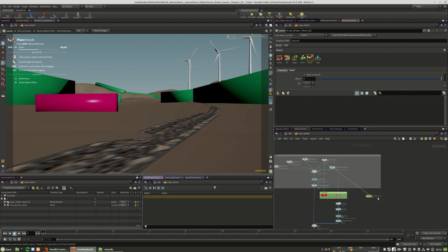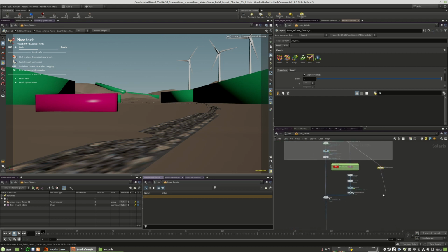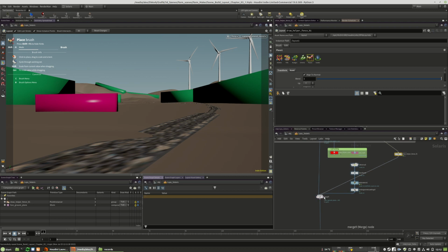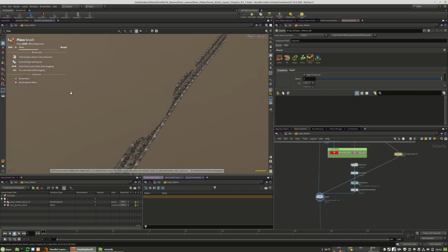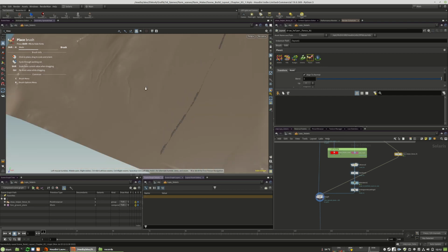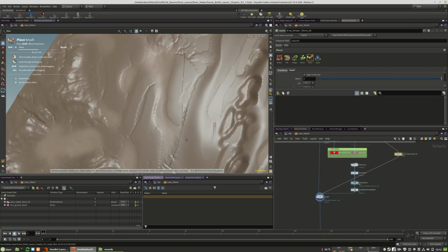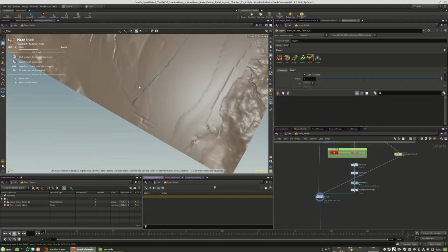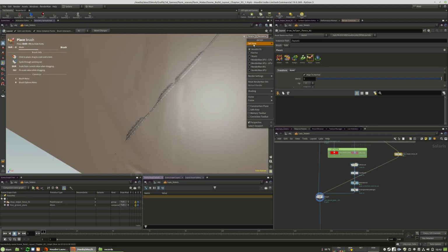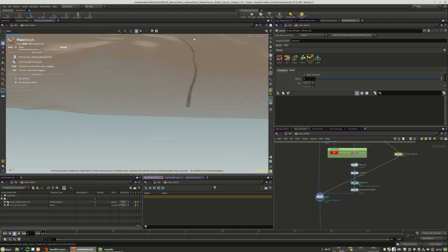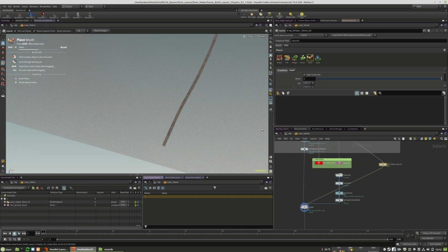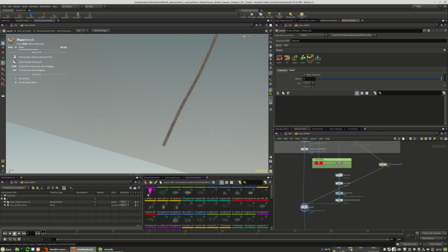Then we will need to check it on our surface itself right here so that we are able to see where we have our road. So the road is somewhere here. And go to a wireframe, makes it easier to see everything. And we go to our layout asset gallery, drag and drop the cones right in here.